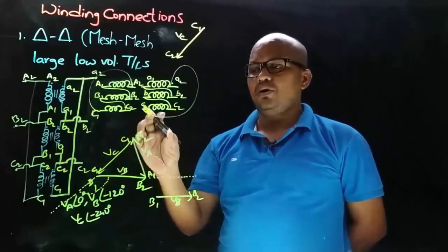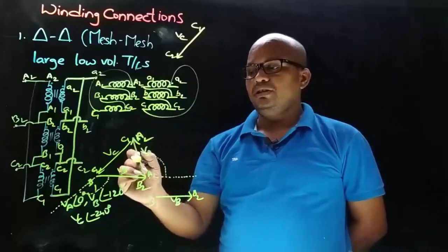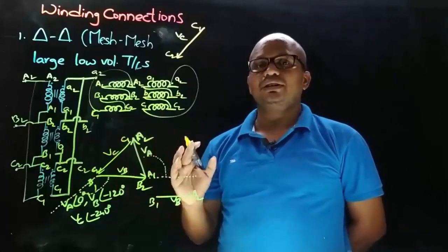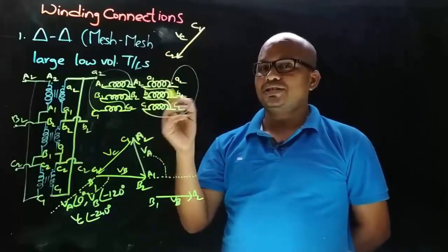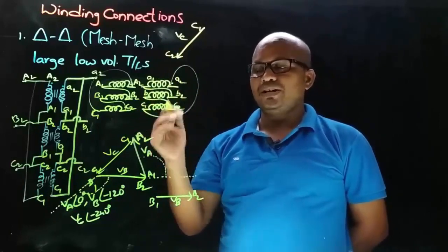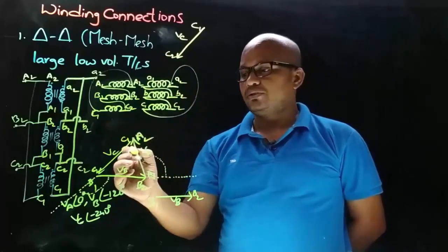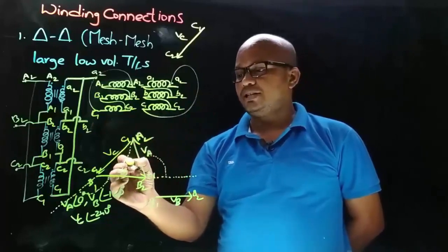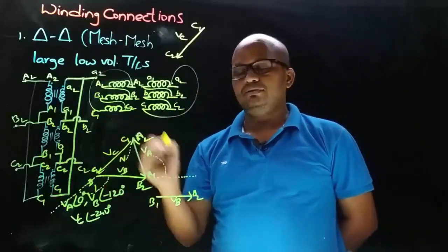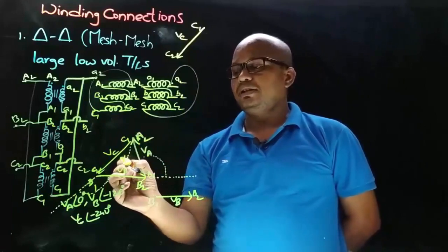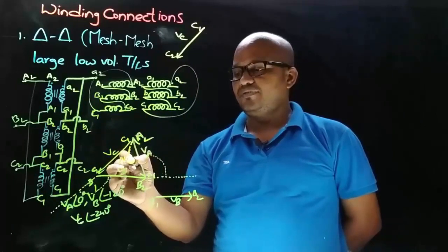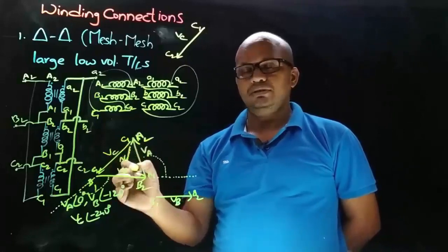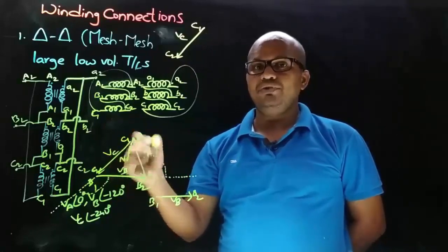And for comparison or reference purposes, here in the delta connection we are taking an imaginary neutral, as we know that a delta connection doesn't have any neutral connection, so we are considering an imaginary neutral. Let that imaginary neutral be here, and that is represented with capital N. Now the reference phasor will be pointing towards the connection we took from.